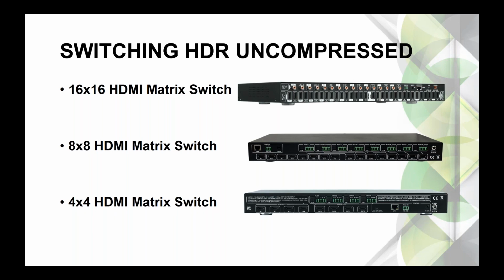Starting with uncompressed HDR, we got 3 versions. They're pretty straightforward. You need AOC cable, a fiber optic cable with Clearline with our transmitter and receiver, or short HDMI cables under 10 meters, or you can use the 444 extenders in here with these. And you can mix and match. These switchers also have built-in scaling, so you can scale the output.